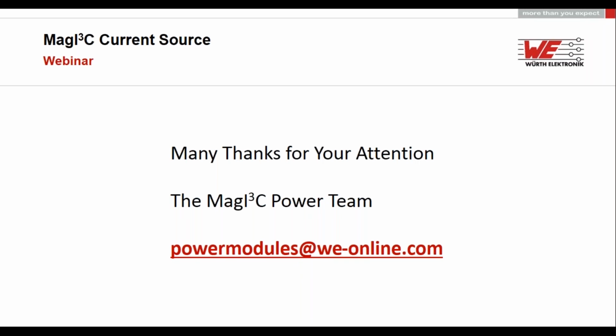Yes, basically this is possible. There are some things to consider, as on these boards we have a switching regulator. If you parallel switching regulators in constant current mode, it works quite well if the regulation loops of each board are slow enough. If not, it can lead to oscillations in between all output voltage lines.